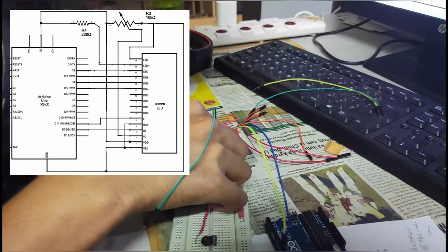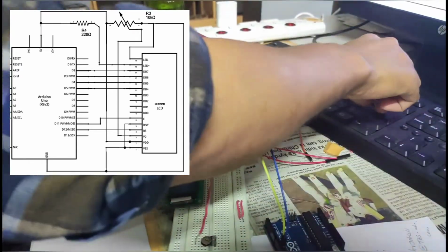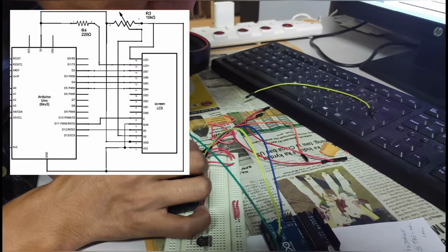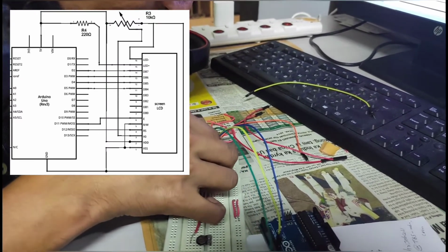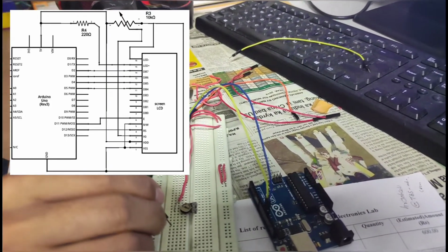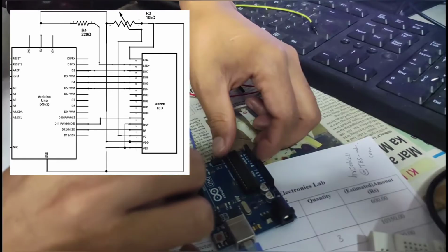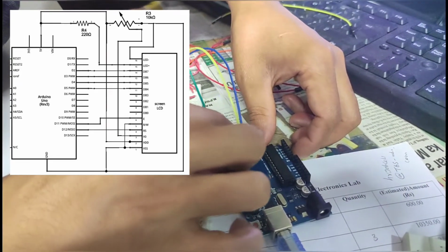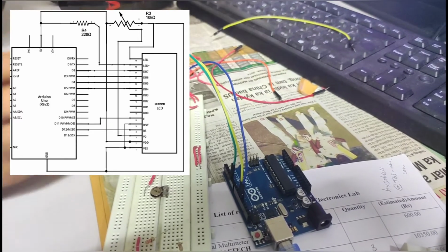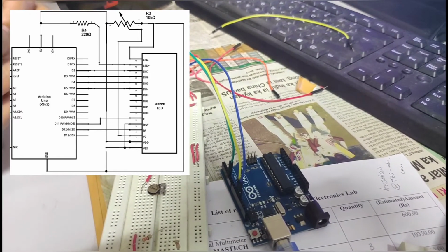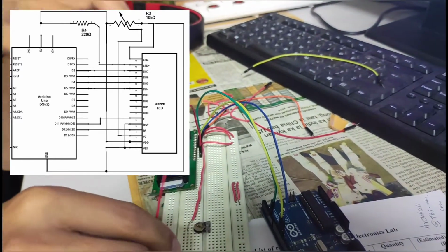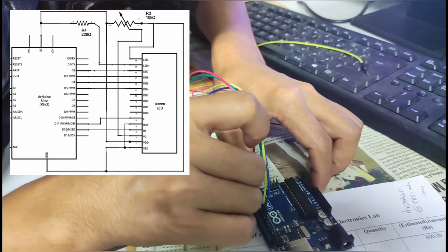From DB4 of LCD, we will go to pin number 5 of Arduino. 7, 6, 5, and then DB5. From DB5 we'll go to pin number 4 of Arduino,